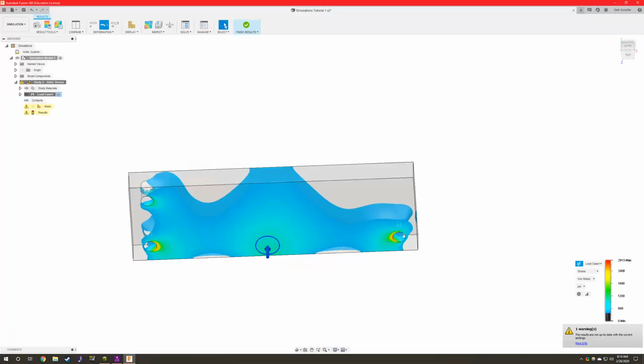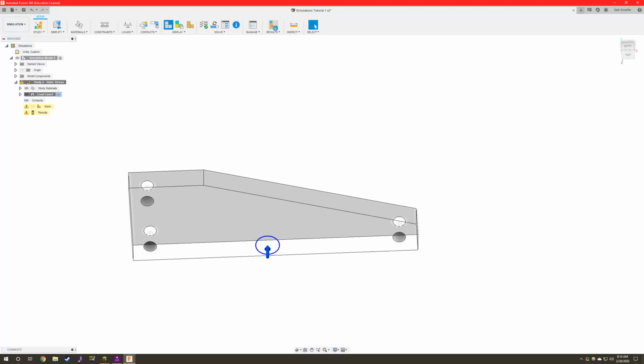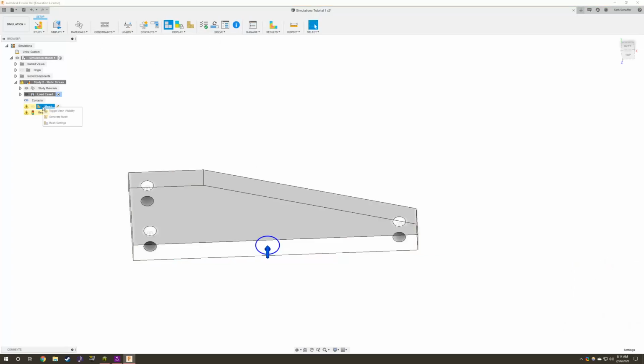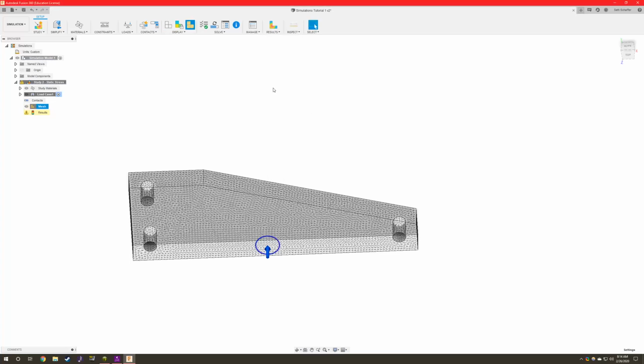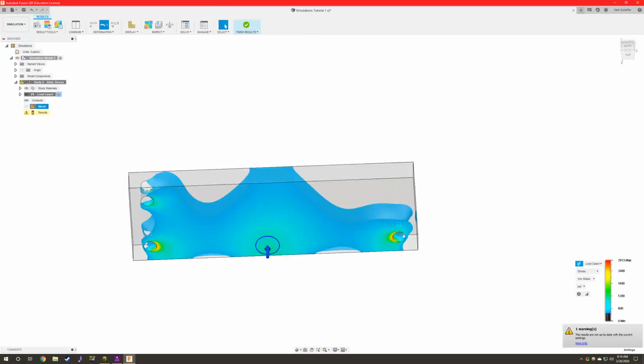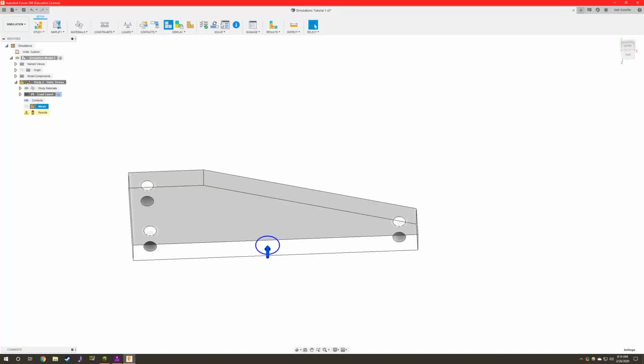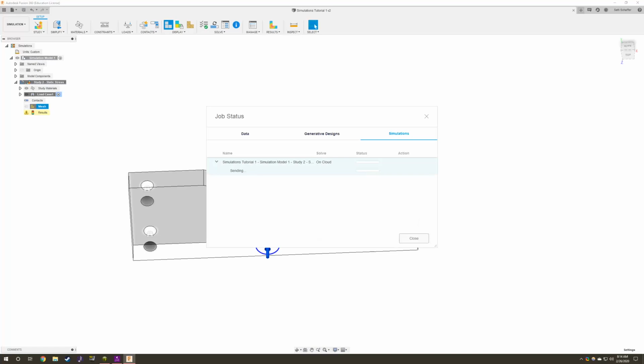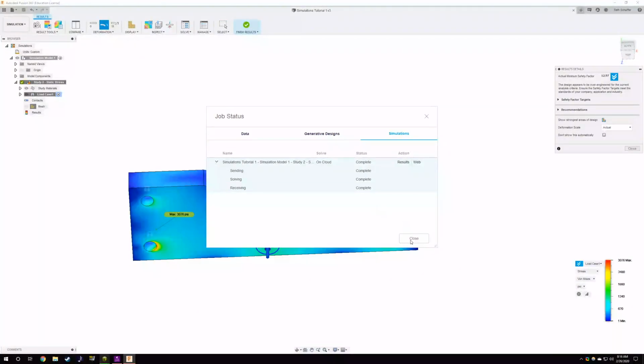And if we go back into simulation, we can simply click results again. Whoops, that's not what we want. We want to remesh, because the mesh is what's actually basically having all the calculations happen to it, not the model itself. So once we recalculate the mesh, we will see the mesh generated correctly, and now we can get new results by actually running the study again. Solve, that's the one. Okay, now we can actually get the results. All right, so now we have our new results here.